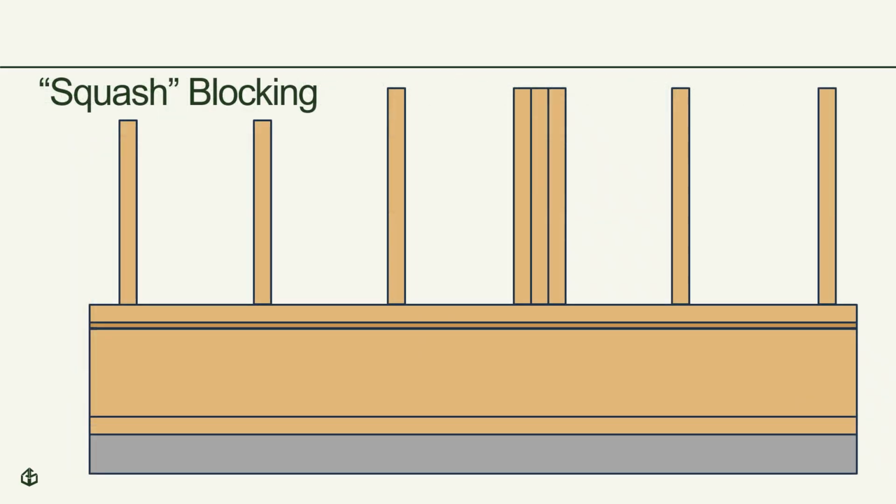Earlier, we traced gravity loads that were gathered up by the header and transferred through the jack studs. This resulting point load needs special attention as we transfer it to the foundation. Here you can see what occurs at the rim joist of the floor system. While the rim board is sufficient to transfer the distributed loads from the adjacent wall studs, a larger point load can be too much for the compression strength of the rim board to handle.